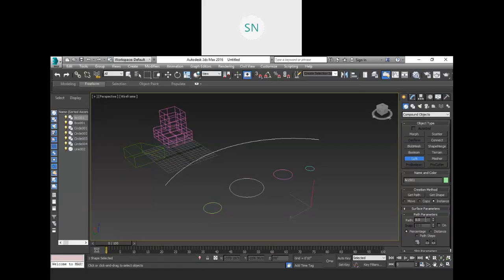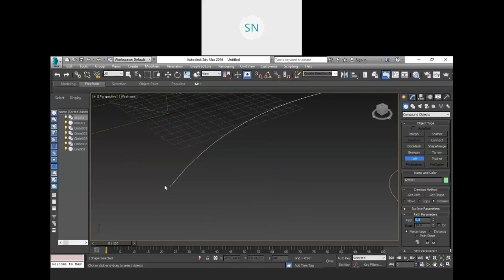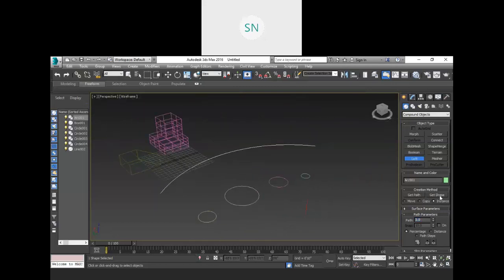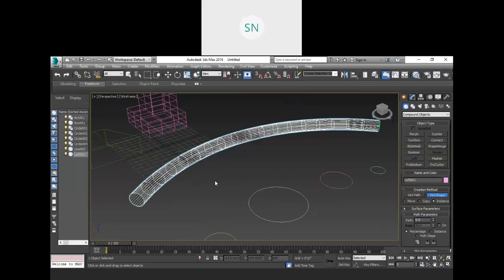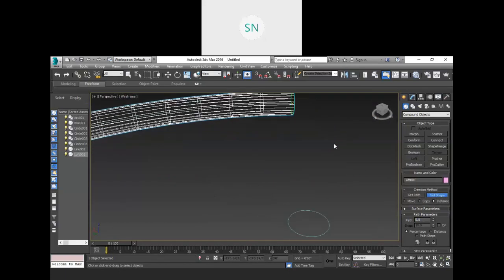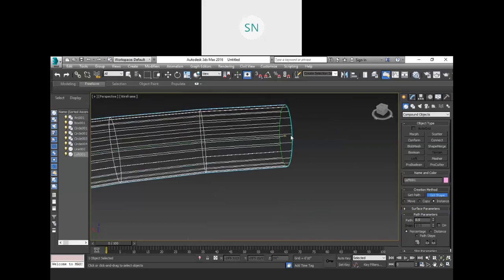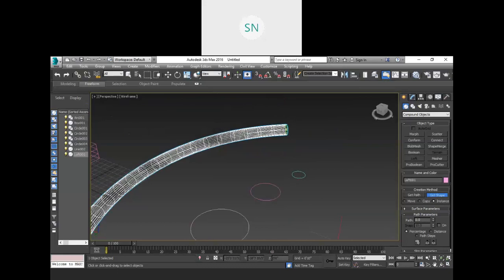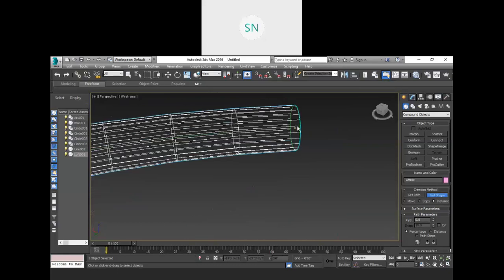Now in the beginning position, the starting position, over here we are going to add one shape. So click on Get Shape, and I want to add this one. It will be at the beginning position, wherever you have this yellow cross. So here we have the yellow cross, and my smaller circle is placed over here.